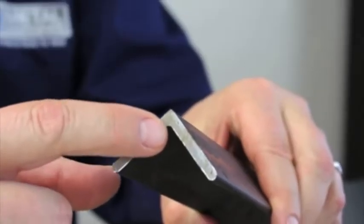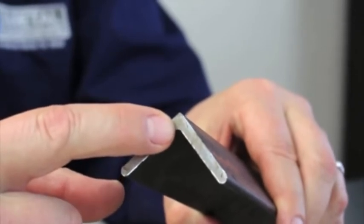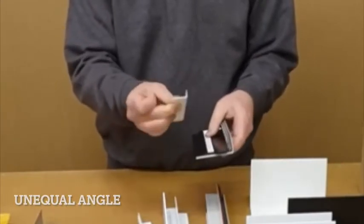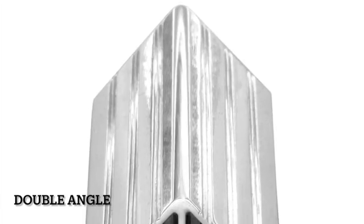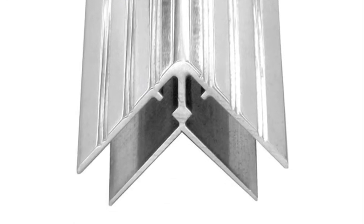There are three kinds of angle. The first one is equal angle. It is an angle having legs of equal length. The next is an unequal leg angle. It is an angle having legs of unequal length. The last one is a double angle. It is a structural member consisting of a pair of angles joined back to back.